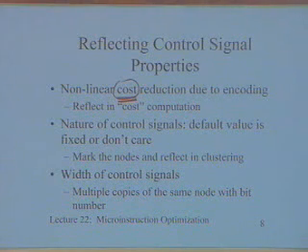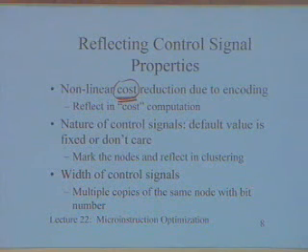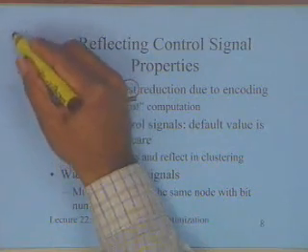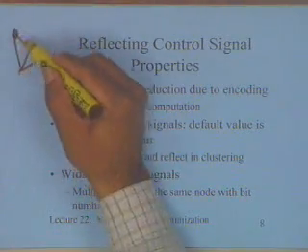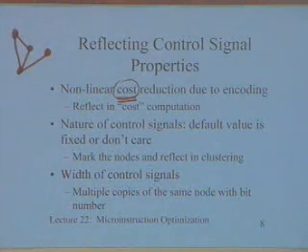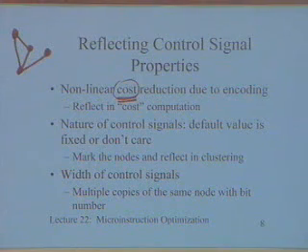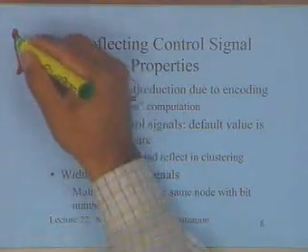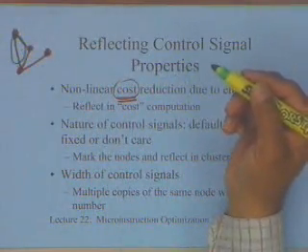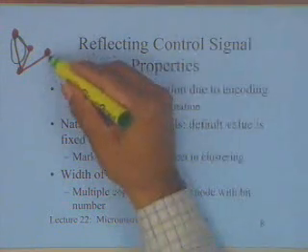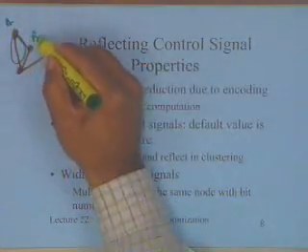It's non-linear in the sense that if you take 2 control signals, you will require 1 bit, let us say. But when you take 3 control signals, you will require 2 bits. When you go for 4 control signals, you still require 2 bits. So for example, if you have a merger graph of this nature, with 4 control signals, and I try to extract cliques, clique partitioning will try to get the maximal subgraphs which are connected, so I may actually end up taking all these 3 together. If I take all these 3 together, I will require 2 bits. And then I will require another 1 bit for the remaining one. So if this is A, B, C, D, let me draw here.